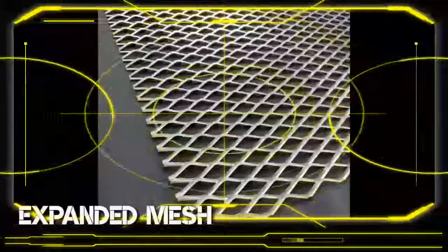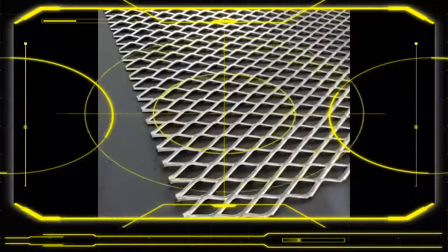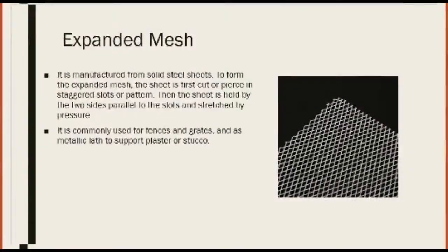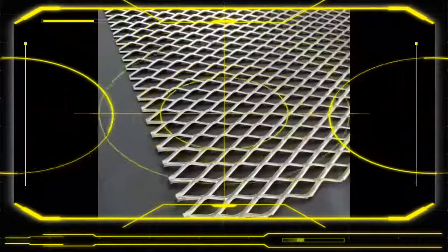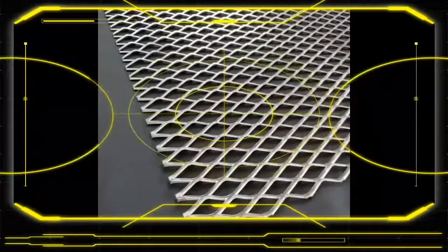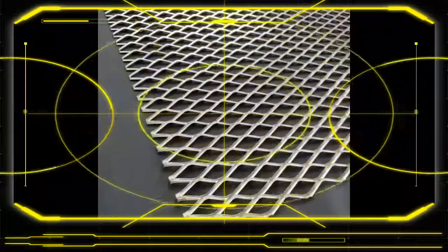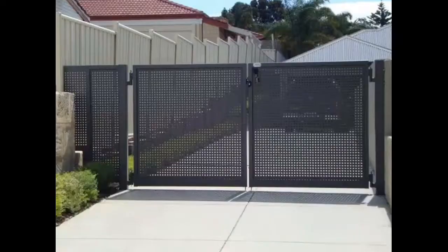The third method for concrete reinforcement is expanded mesh. It is manufactured from solid steel sheets. The sheet is first cut or pierced in a staggered slat pattern, then the sheet is pulled by the two sides parallel to the slats and stretched by the pressures. So basically, it is a diamond-shaped wire fabric. The pattern here looks like a diamond-shaped window in this formation. It is commonly used as metallic lath to support plaster or stucco. Aside from concrete, it can also be used for fences or even gates.